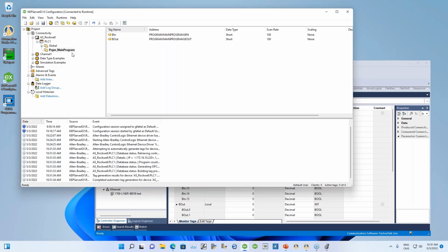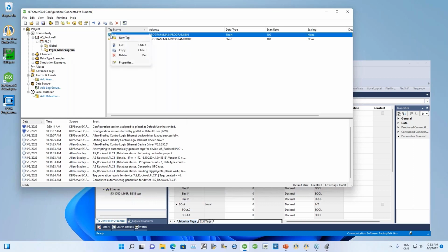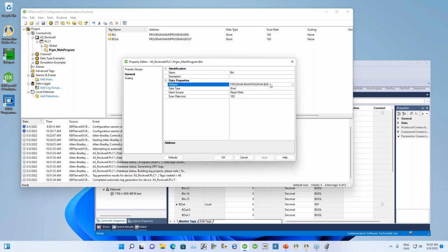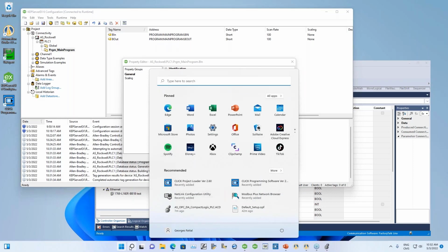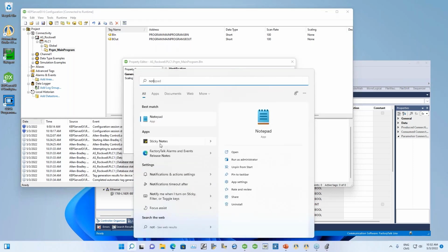By the way, this is OPC. What we are showing over here is the standard in OPC-DA, and it's very important to understand that because what we do over here, we're going to repeat for all the other PLCs if you ever want to dive into this technology. So here, if I look at the tag, at the end I see properties. So you see here, I'm going to copy this. I'm going to open Notepad, for example, to show you a part here.